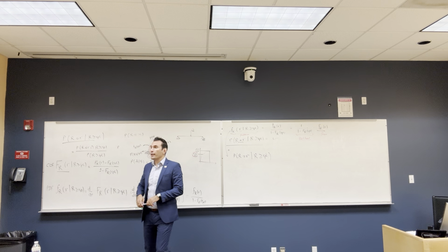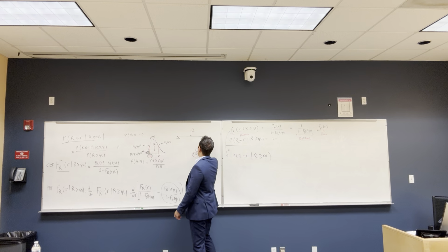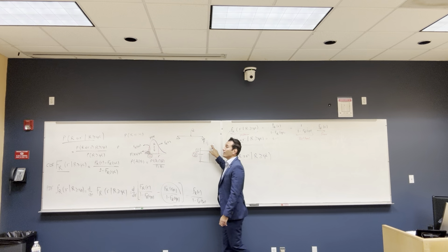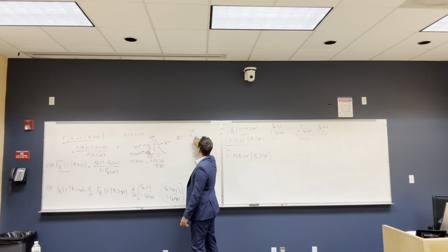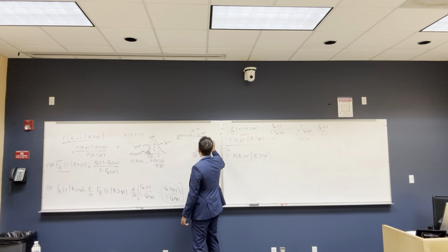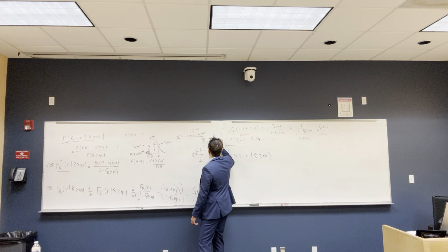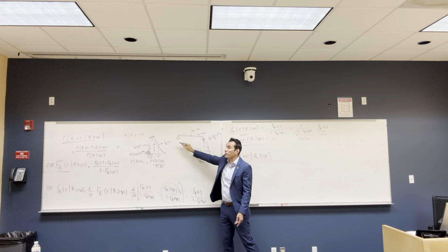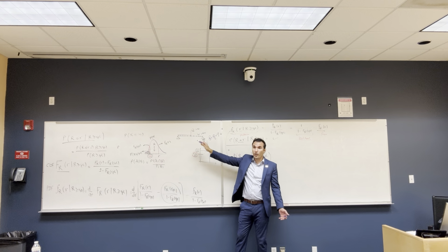Let's say that you have a beam with a load Q, and you try to find the load here. The load here is Q over 2. That's still a random variable. If you put a distributed load W, Q is a random variable, and W is a random variable, and the load here is going to be WL over 2. So the reaction R, which is equal to Q over 2 plus WL over 2, is still a random variable because it's a function of two random variables. What are these two random variables? Q and W. L, the length of the beam, is deterministic, not a random variable.